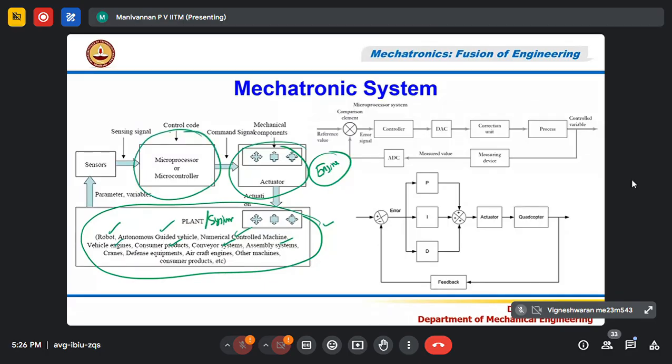The controller is nothing but a small computer which has a CPU, like your laptop or desktop. It has a CPU, it has a memory in which you store the program. An operating system will be there, which is called RTOS, real-time operating system. Generally, in your computer, you have the general purpose OS, GPOS. General purpose OS is like Windows, Ubuntu, or any computer you are seeing anywhere. It can be a laptop, desktop, mini computer, supercomputer.